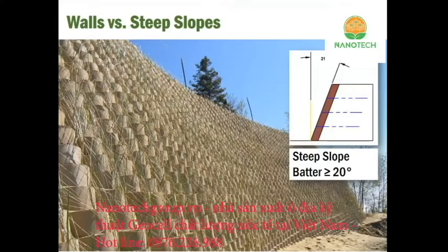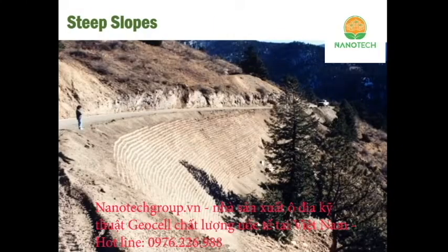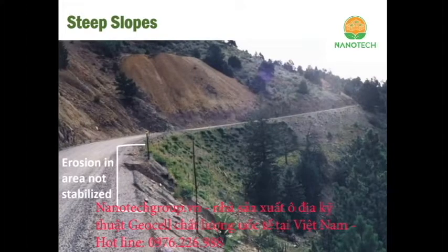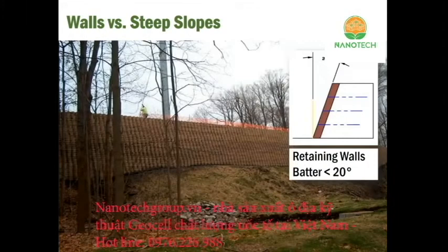Walls, we think in terms of bearing capacity, overturning, and sliding. The biggest benefit is the ability to build a solution that fits well with the surroundings and doesn't look out of place. Steep environment. They also note erosion in this area is not protected by the GeoWeb system. Another advantage of the steep slopes is that vegetation can flourish within the geocell slopes because there's more horizontal.